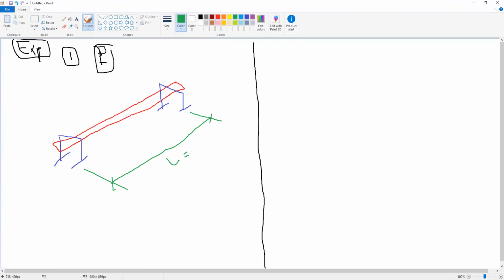And if you measure the dimension of the beams, all of them will be 900 millimeter, just to be comparable to each other. All of them with the same length. Okay. Then at the middle, or at the mid span, you should set up your dial gauge, and you need to re-zero it each time to record the deflection.